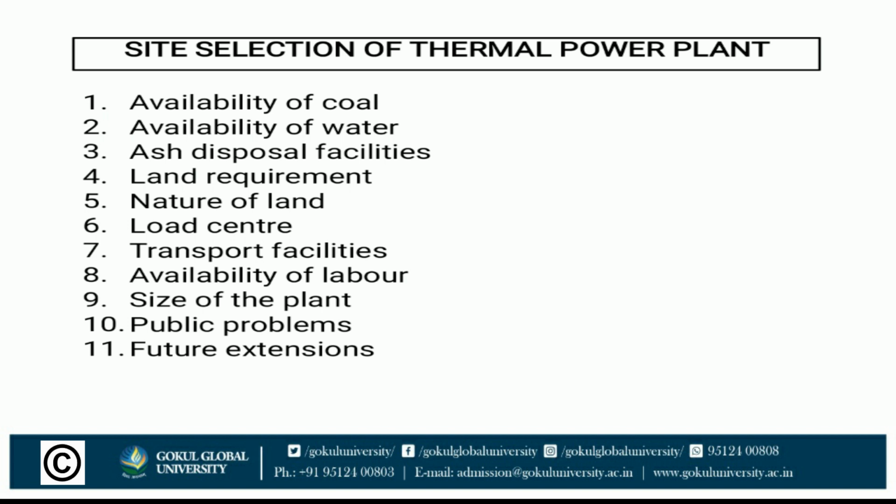Second one, availability of water. In the steam power plant, water and steam are the working fluid. Hence, a large quantity of feed or makeup water is required. Also, a huge amount of water is required for the condenser, cooling tower, and for disposal of ash.